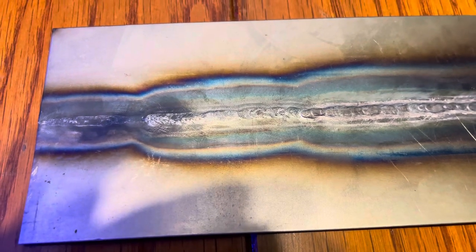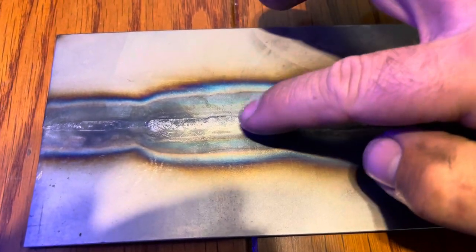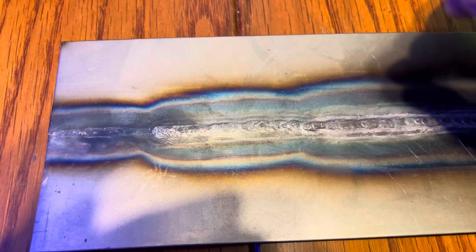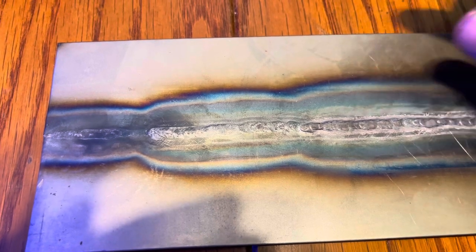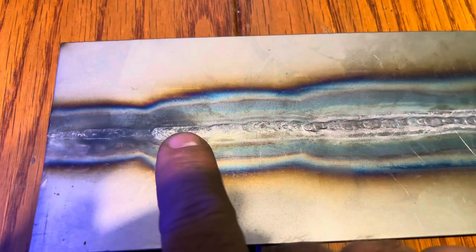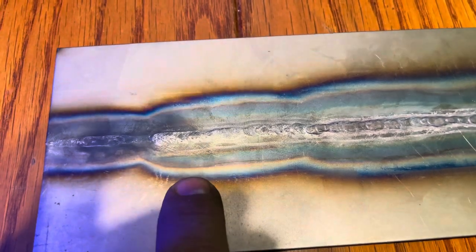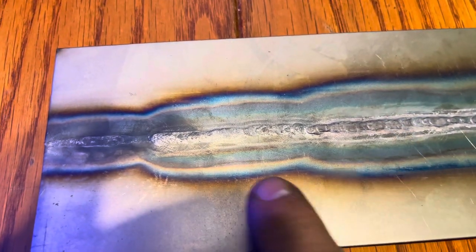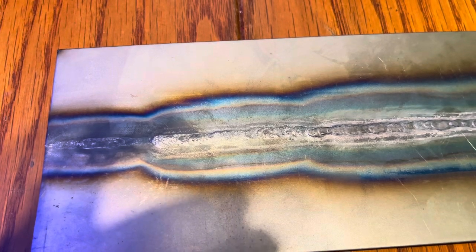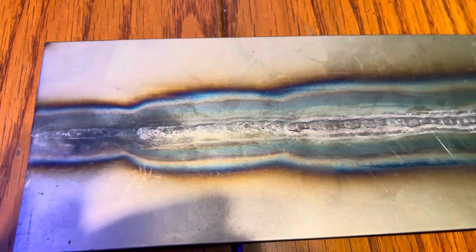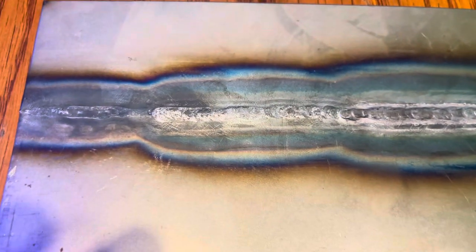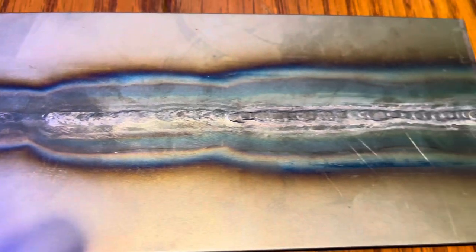What was changing the temperature of the puddle and causing more time was that the filler wire was cooling the puddle off. That way we could see how filler wire affects the puddle. We could also see what time does, because time is going to give us that thermal conductivity. And this is the best way that I could feel to show an example of that.